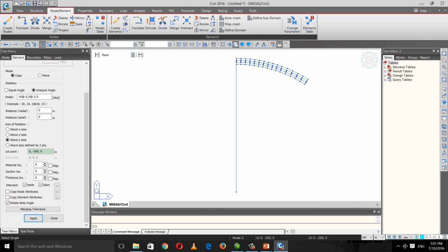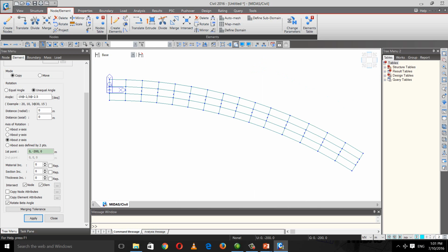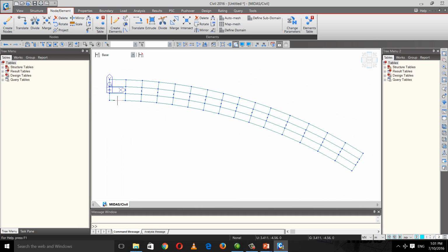Okay, and so after generating this, I can just simply delete this, I don't need this one, and you can see the grillage is generated. For skewed bridges, all you need to do is just move the coordinate points a little bit and then further subdivide the elements in between, and you have got the bridge generated quickly. Okay, so this ensures that you have got a proper spacing of the transverse elements. You can assign the properties correctly to the transverse elements based on the spacings here.